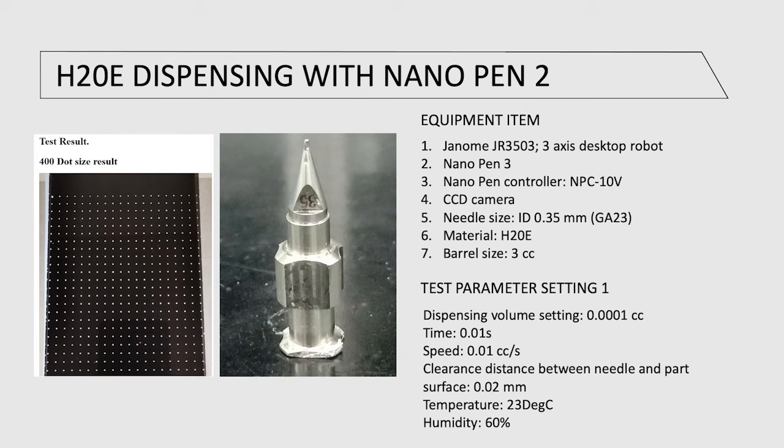Given our results, we repeated the testing with a nearly identical setup, same epoxy, same settings, needle tip, the main difference being a decrease in the back pressure. With time pressure dispensing systems, the back pressure is a critical factor, and we typically advise customers use a surprisingly low back pressure. The lower the pressure, the lower chance of silver agglomerating in the needle tip. If silver starts to agglomerate and back up the needle, that can lead to smaller dot sizes, bubbles, or bursts, which may look like a dot skip.